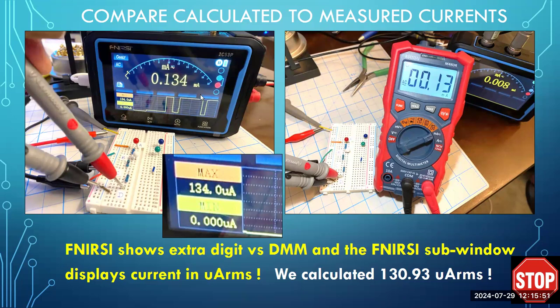And keep in mind, both of these measurements, on the digital multimeter as well as on the tablet, are measuring AC, and you can see AC on this right here. This is not measuring DC, it has AC on the screen. And the same thing is true here, this has AC on this screen. So it's measuring AC in the form of RMS. Neither one of these is showing peak current. These machines are not designed to show peak current. You can see RMS current as we have calculated, and it shows up very, very nicely. Okay, so this is the current measurement of the tablet oscope. And let's go ahead and do this.